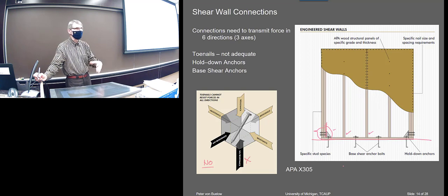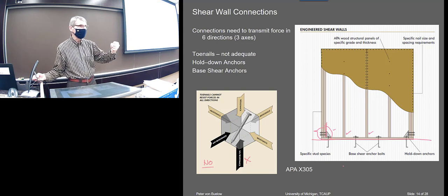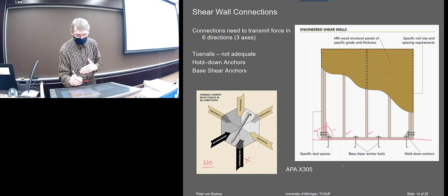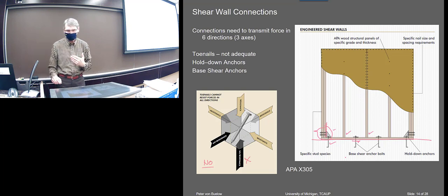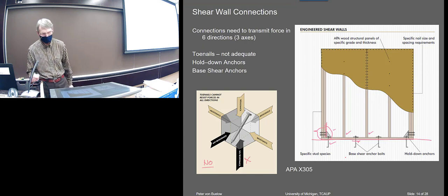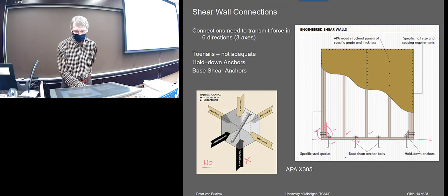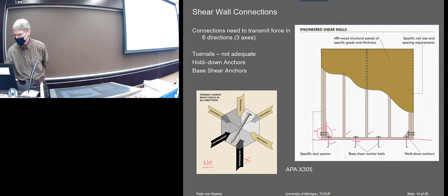If you just drill them, I don't know, you have to look up what the strength is, but they have a pull-out strength. That's critical for this one, that pull-out strength. These take primarily a shear force on them, so that's not quite so critical. I guess maybe you could get away with drilling those, but very often they're cast into a slab.